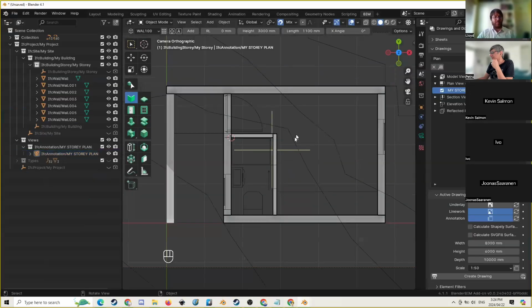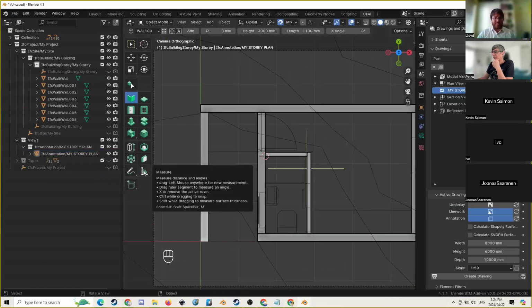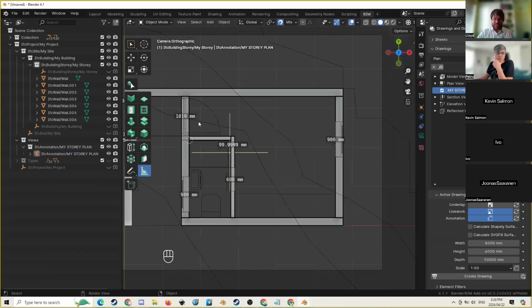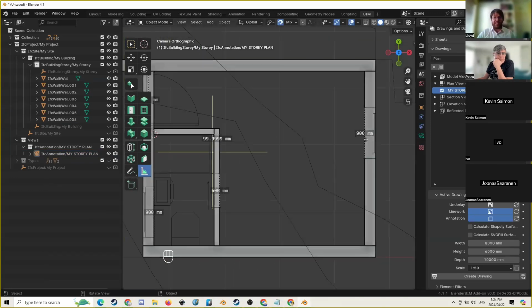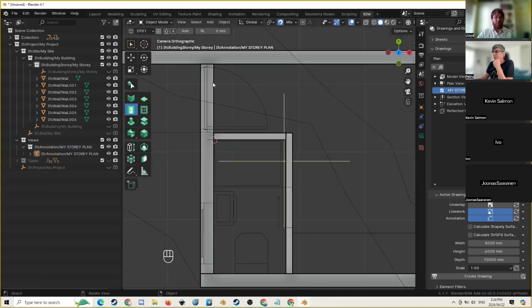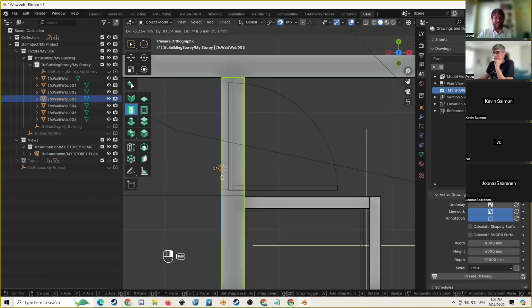Right. So from there, we want to do these doors and windows. And we can just check the sizes by clicking on the measure tool. Okay, this is about 1,000. 1,010, I'm just going to make it a meter. And then this one is 900. So I'm going to go to the door tool, create door, door type 1. I'm going to select this wall, not the DXF, but the wall itself. So it's green. And then I'm going to snap to that point.